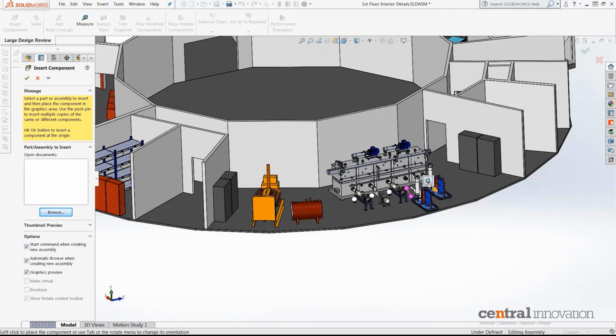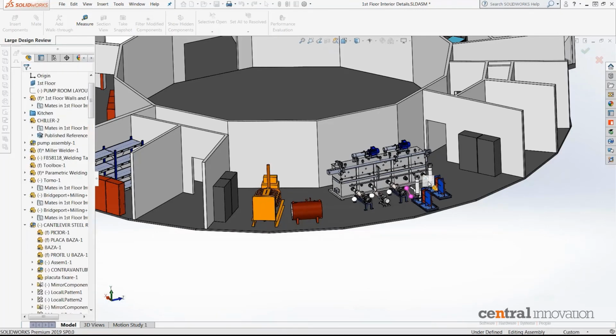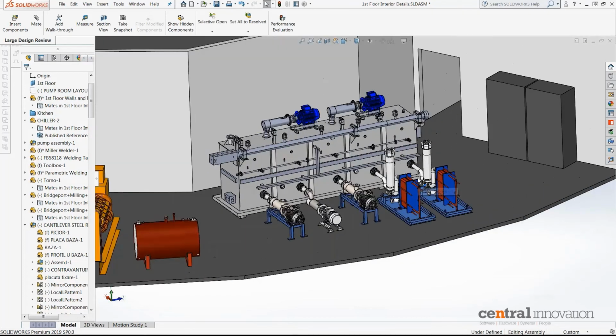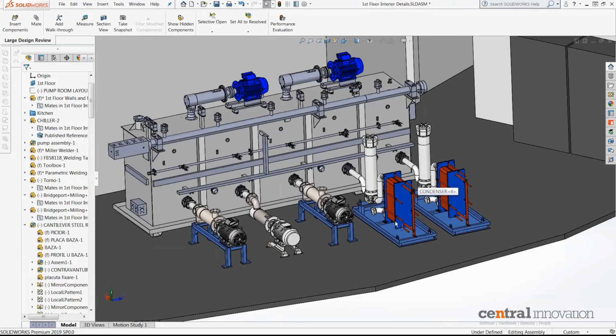after a short wait there, you just click on the magnetic mate button. You'll see that it's positioned it alongside the other condenser using magnetic mates only, so it's fully aligned that into position, which is a real neat time saver if you set those up.